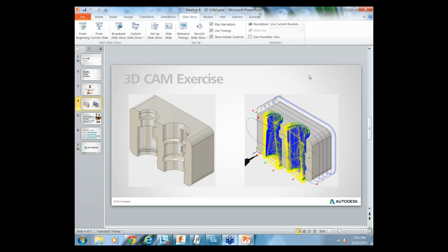We would run it in wax, and when we get a good one, then you can go and run it in the actual material. Machinable wax is awesome if you check on the feeds and speeds, but if you, for example, run in metric instead of inches, it will run inside of the wax no matter what. So machinable wax is awesome, but it doesn't protect you from everything. You would still crash your space probe onto Mars, even with the wax.